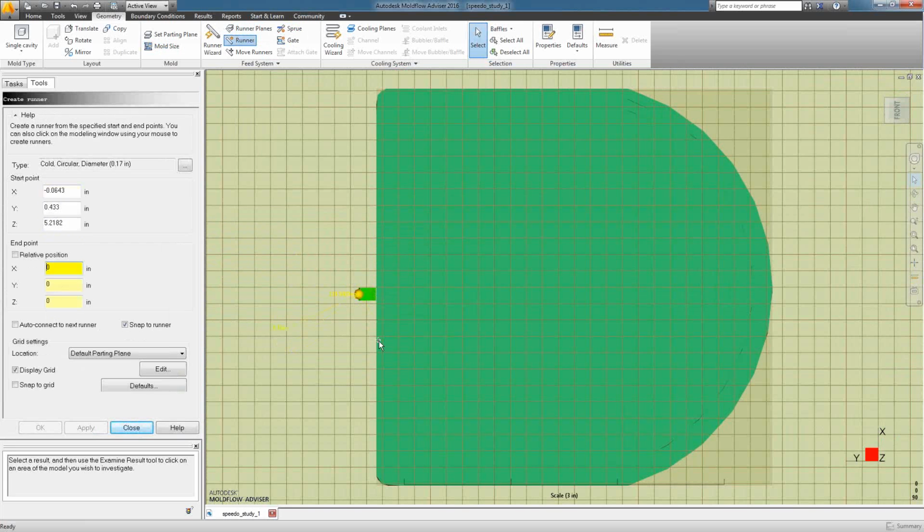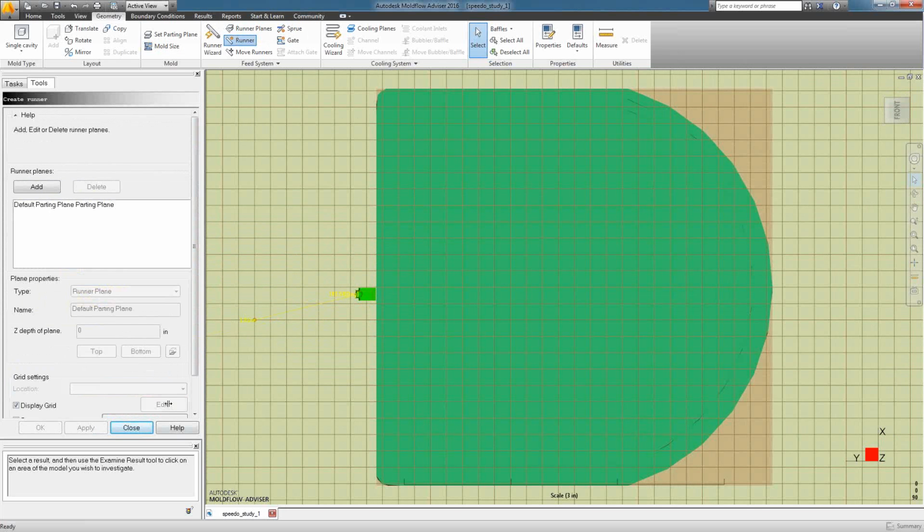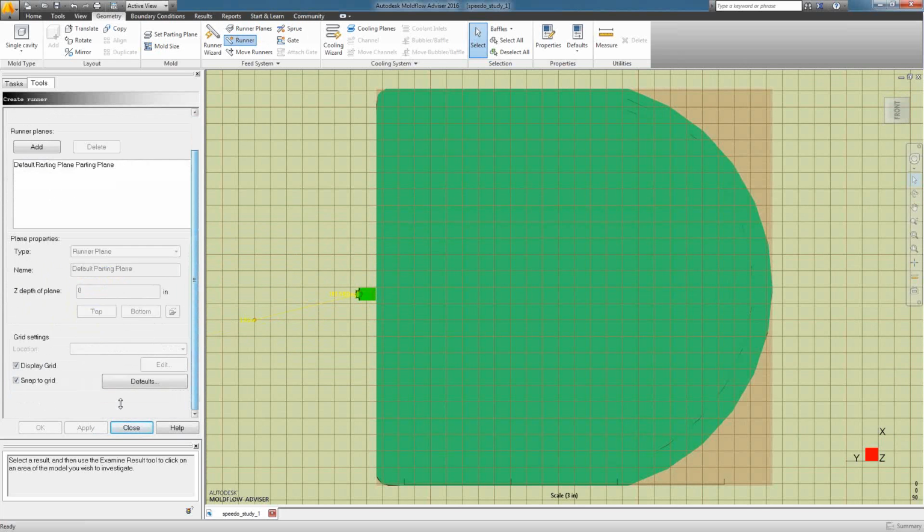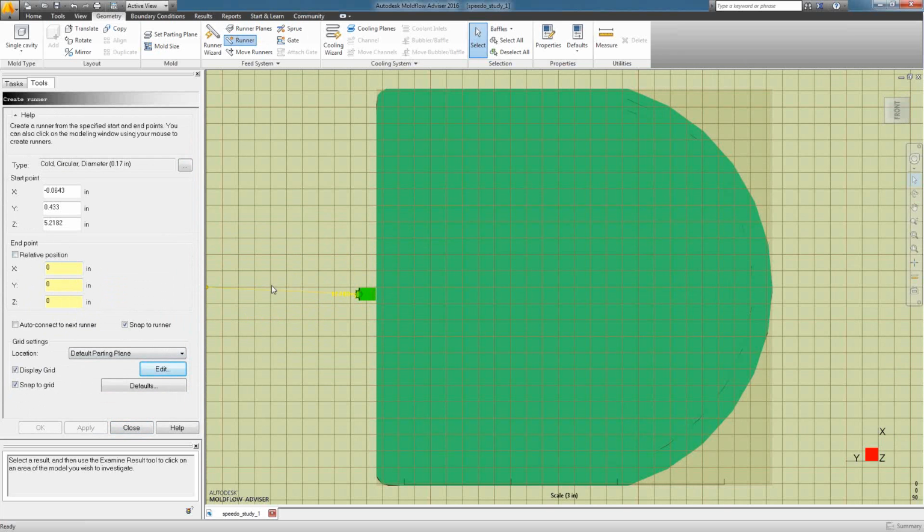If you click on that, you're able to adjust this around as much as you want. You can click on Snap to Grid and make any adjustments to the grid if you'd like, so change that around. But again, for this demo, I'll keep that the same here. And what I'll actually do is use a coordinate rather than just click any random place here. So to keep it a straight runner, I'll go ahead in the positive Y direction. Let's say 2 inches.